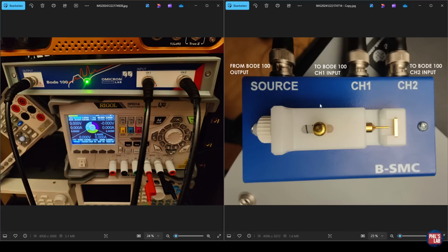This impedance adapter contains a few different components as we saw previously and can house an SMD component. We have this spring contact which we can hold in place with this adjustable screw nut. And on the right hand side we have two contacts, one the spring loaded one on the left, and on the right hand side this plate which is just a gold contact plate. And by releasing the spring contact we can then clamp in an SMD component, which is exactly what we'll do.